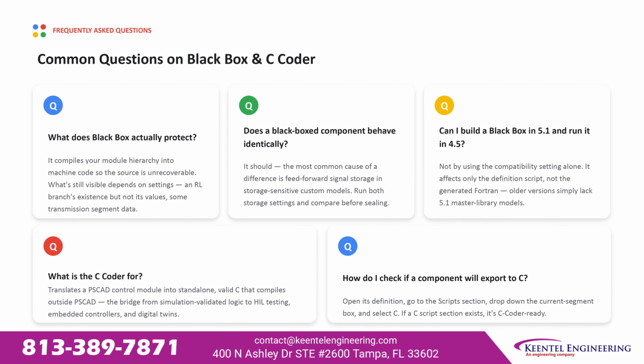Can a black box built in version 5.1 be run in version 4.5? Not by using the compatibility setting alone. That setting affects only the definition script, not the generated Fortran. Older PSCAD versions simply lack the version 5.1 master library models the component depends on.